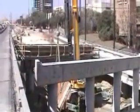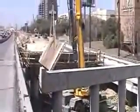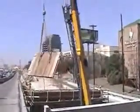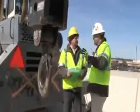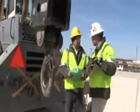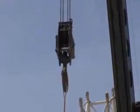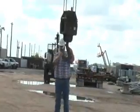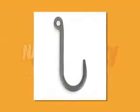A lift is successful only if it is completed without harm or injury to anyone or damage to anything. The following steps are important and recommended to ensure a successful and safe lift and landing of the load. First, determine the weight of the load, then determine the appropriate type of sling and the proper hitch to be used for the load. The load center of gravity should be directly below the hook. Before hitching the load, check the hook for problems. Make sure the safety latch is in place and working correctly. Hooks with self-closing latches or their equivalent must be used unless setting wood trusses in which J-hooks are permitted.